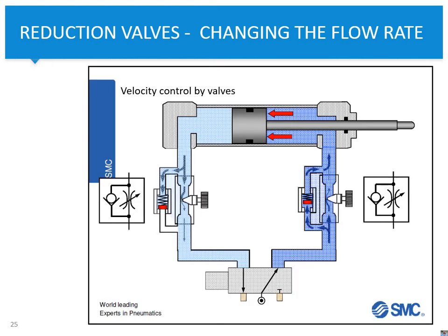And here I have one last example of this. Actually, this one is used by SMC in a double-acting cylinder to make it run smooth. Let me draw this. There's a flow coming from a certain pump over here, and it's going through this valve, through this hose, and then it's going to flow directly through this directional valve into the cylinder rod side.